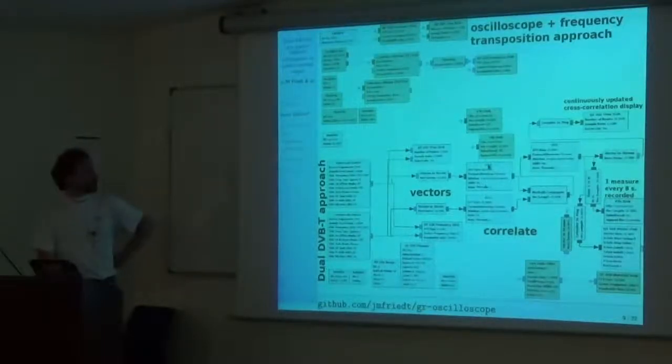As Paul just showed us, if you want to take a Fourier transform, you need to accumulate enough data to compute the correlation. So you first convert your stream to a vector. The length of the vector is the equivalent of a pulse repetition rate when you're talking about radar, so how often you do the measurement. You convert the stream to a vector, you take the Fourier transform, and I'll show you tomorrow during the tutorial that by taking the complex conjugate multiplication of the Fourier transform of a reference signal with the Fourier transform of a measurement signal, you get the Fourier transform of a correlation. So you can implement correlation with this Fourier transform block.